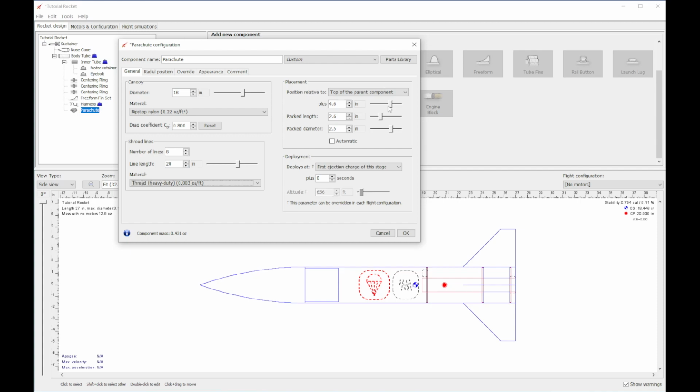Packing harnesses and chutes isn't a super exact science in a model like this. If you are using deployment bags or have very specific location control for your recovery gear, obviously take the time to take more precise measurements for these because they're definitely going to contribute to your center of mass as it's calculated in the model here. Okay, I think that's good for parachute.